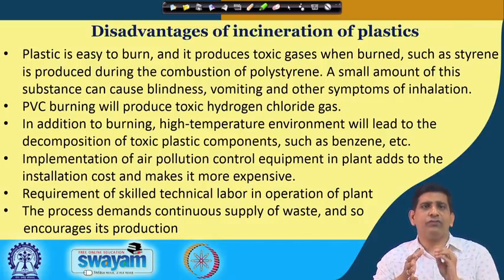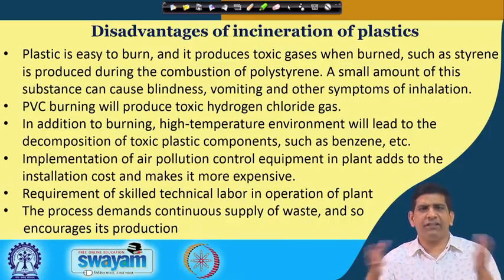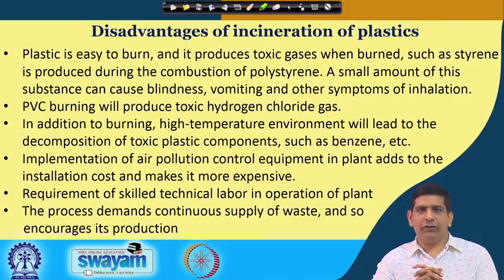The issue for waste to energy plants, as we just discussed a few minutes back in the Indian context, is that since the calorific value is so low, it becomes difficult to manage this kind of waste in general. Plastic does not come in isolation. Plastic is there with your papers and other stuff, and since we have food waste, yard waste and street sweepings, everything mixed together, it becomes a problem in terms of low calorific value, and those plants do not really work very well from an economic as well as operational point of view.